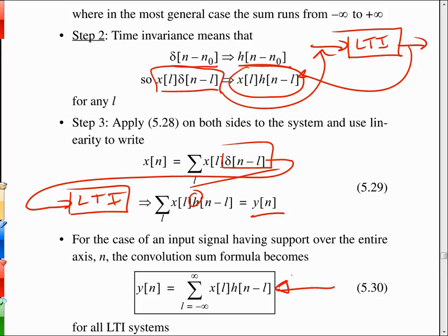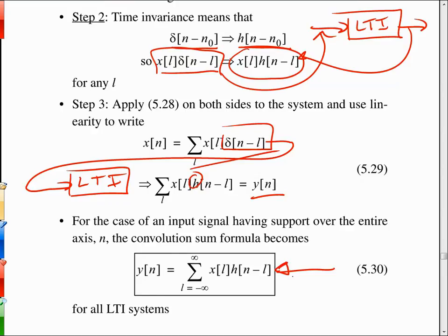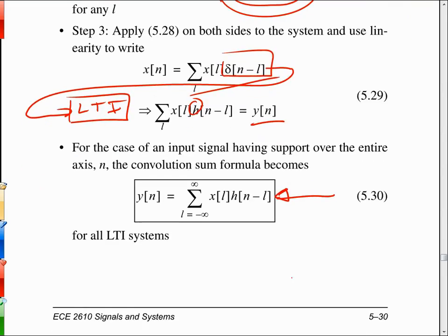So when you think of an output of a filter, it's like I'm superimposing all of the time-reversed impulse responses that have been shifted out to different locations, and then applying a gain scale on each of those, which is whatever the amplitude of the input sample was at that instant, and then adding all of those up, and that becomes the composite output. But when we think of the mechanics of it, of course, in this equation 530, we did that with the table method, right?